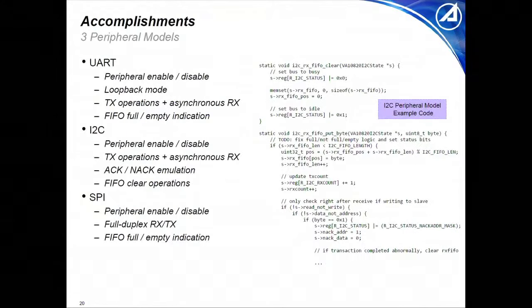All right, so what did we actually do? Well, we wrote some peripheral models as planned. We really just made it to the bare bones functionality. It was enough work to dig into QEMU on a Monday, try to figure out how this large code base works and how to plug into it, so that by Tuesday or Wednesday we were able to issue reads and writes from our flight software running on QEMU and see that they were making their way into our stubbed model.